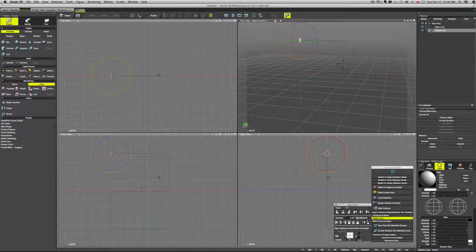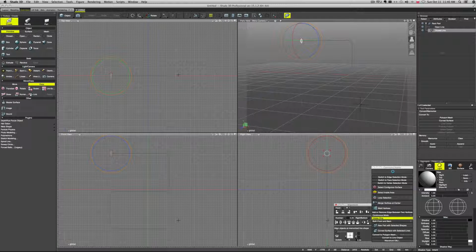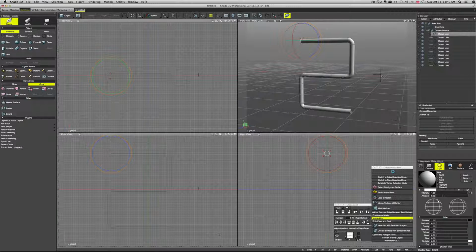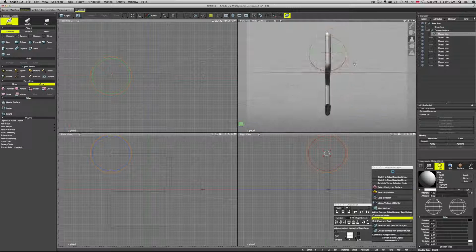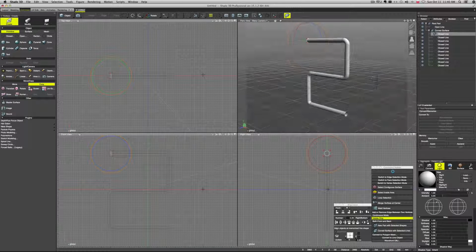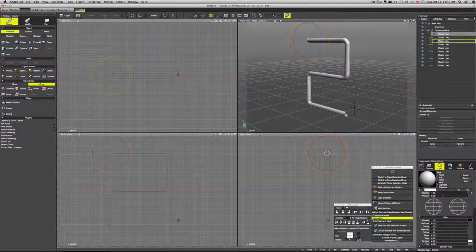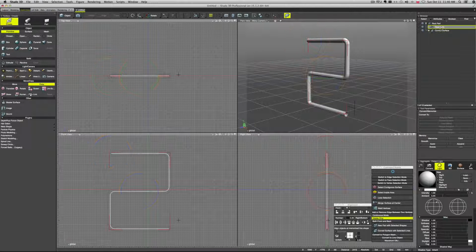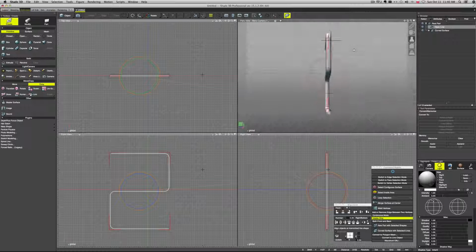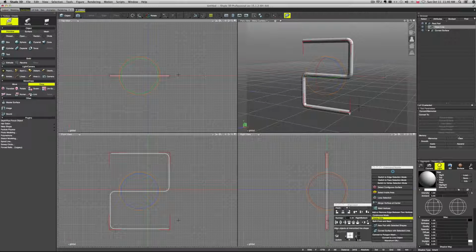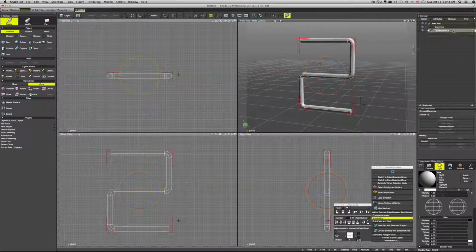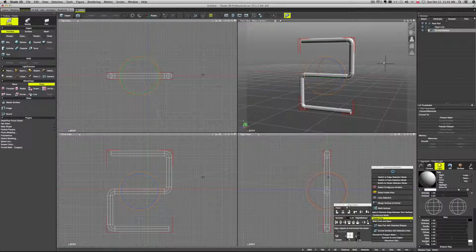Now that we have it at the beginning of our path, let's click sweep that we have here in our parameters. And as you can see, it just automatically sweeps, creating this whole bunch of closed lines and putting them all in a group. So now we can clear this memorized line, and basically we're done.